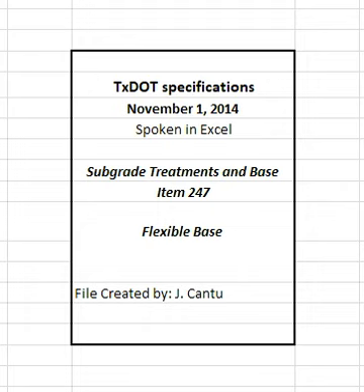2.1.3.1 Limits on percentage. Do not exceed 20% RAP by weight, when RAP is allowed, unless otherwise shown on the plans. The percentage limitations for other recycled materials will be as shown on the plans. 2.1.3.2 Recycled material, including crushed concrete, requirements.